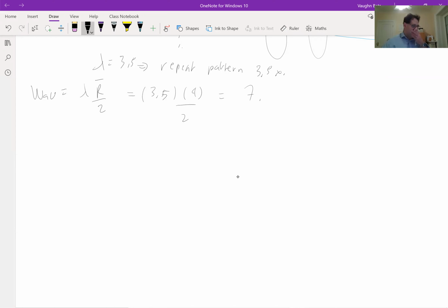Okay, so 7 wires per channel. But we can't use all the wires in a channel, at least not everywhere, not in the typical case. You might be able to do it once in a while in one spot in the chip, but you're not going to be able to do that very often. You kind of got really lucky.